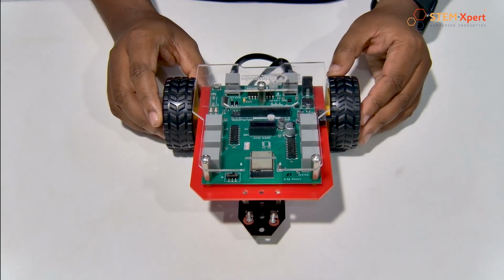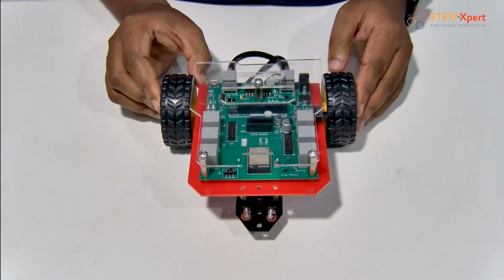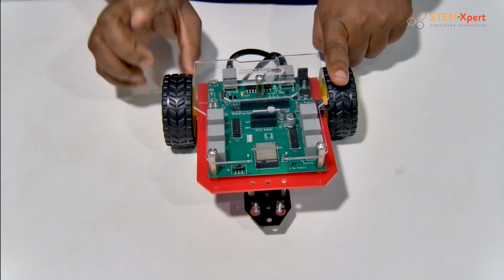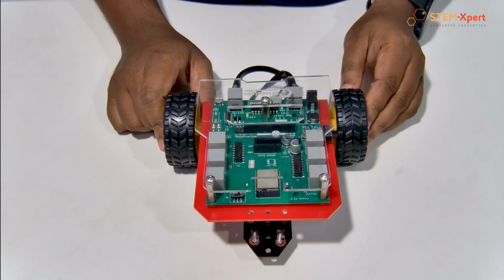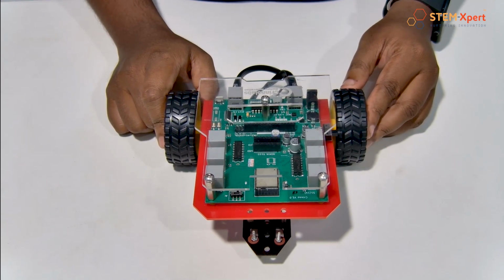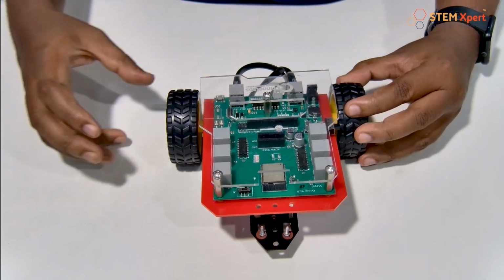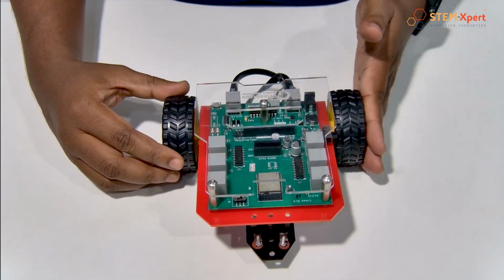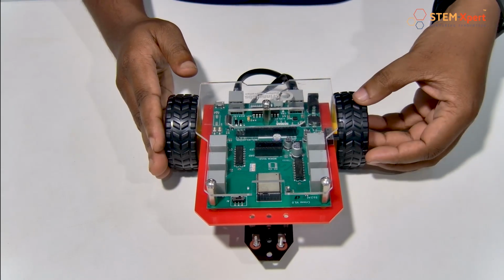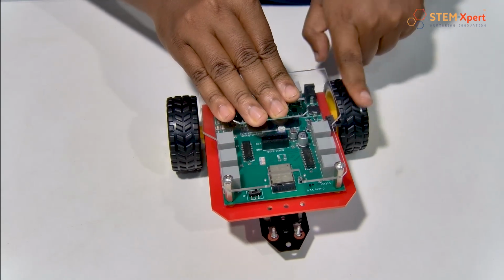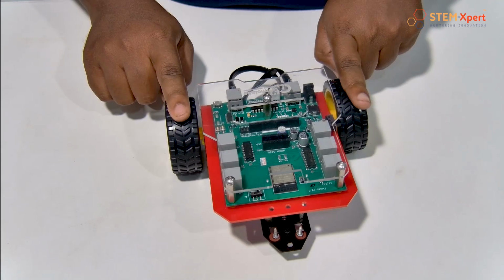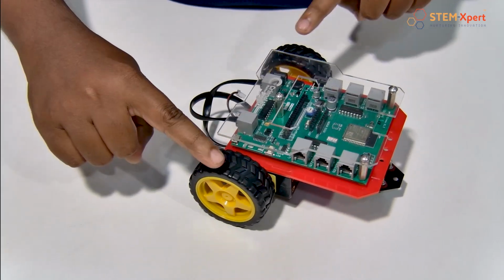Now what did I say? If you really want to turn left, we have two options. Let's focus on the second one, which means this has to move backward and this has to move forward. If you want to rotate left, just set this motor to rotate backward and this to move forward, which means 0, 1, 1, 0. You got it, right? Don't be confused. We set 0, 1 and it will move backward, and on the right side the tire will be set to 1, 0 and it will move forward. Now look at that. Wow, it will be making a left turn, right?